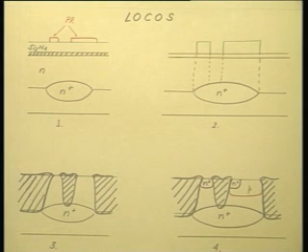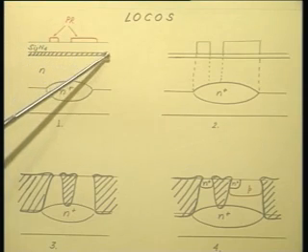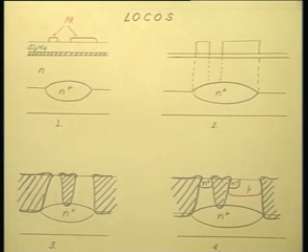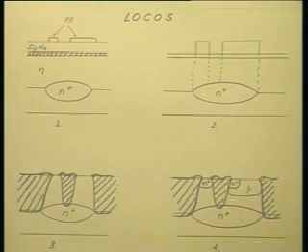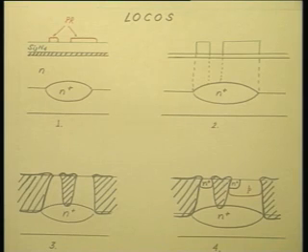What do I have? I have as before the p-type substrate, I have the n plus buried layer, and then I have the n epitaxial layer. So far nothing has changed. So far my technology is exactly the same as the older day bipolar junction transistor. After this, of course, what have I done? I have a thin layer, this black hatched region, this is the thin layer of silicon dioxide, which is called the pad oxide. On top of the pad oxide, I have silicon nitride,